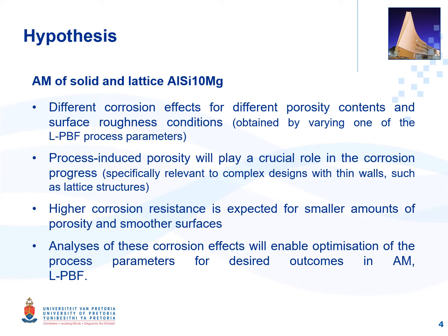Process-induced porosity will play a crucial role in the corrosion progress, specifically relevant to complex designs like lattice structures. Higher corrosion resistance is expected for smaller amounts of porosity and for smoother surfaces. And analyses of these corrosion effects will enable optimization of the process parameters for desired outcomes in additive manufacturing and laser powder bed fusion.